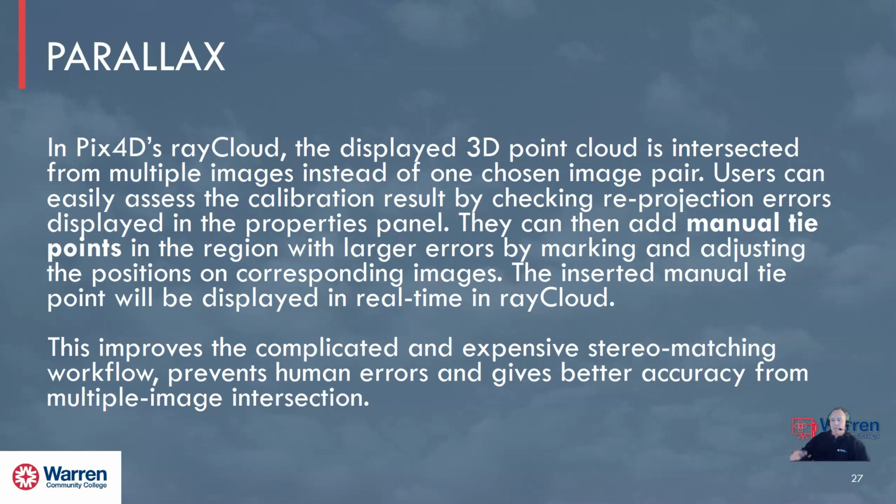So what does that mean? That means if I do have measurements on the ground that are either exact GPS locations that have been pre-measured, or scalable measures where I know the distance I've measured between 2 points, or I've laid out a tape measure, and if I put enough of those down, I can diminish these errors right in PIX4D by saying, no, this is really your estimation of where this image is, really 2 inches off in this direction.